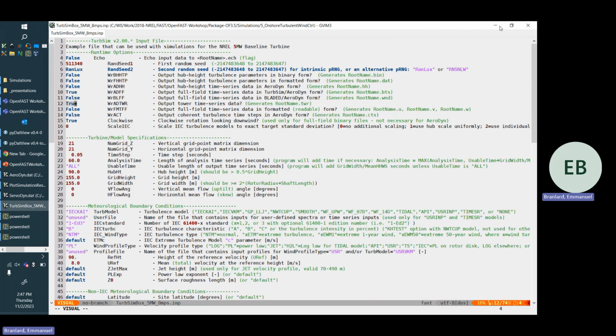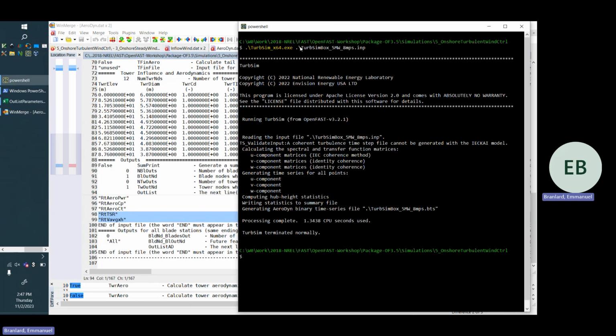I use a GitHub repository for everything I do. All my FST and my DAT files are in a GitHub repo, so that if I do a demo and start changing an input file and forget about it, and then my results don't match anymore, at least Git will tell me, hey, you changed that file. That's definitely top on my list of recommendations: always have GitHub repositories for all of your work. You just exclude the output files. Don't put the output files in the GitHub repo. You ignore them, right? But all the rest should be in a GitHub repo, your scripts and input files. Good question.